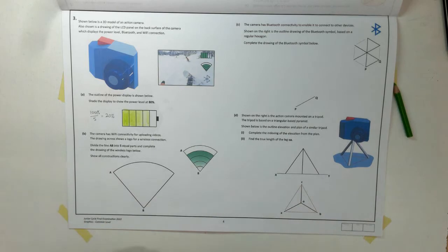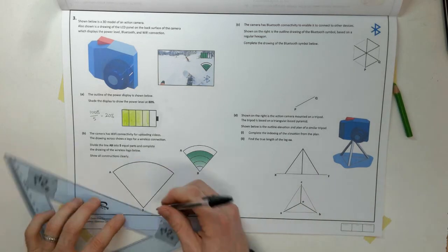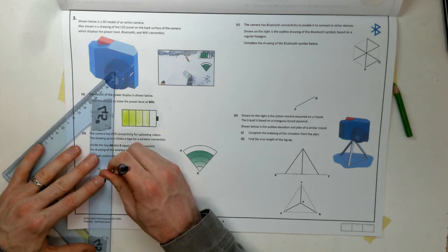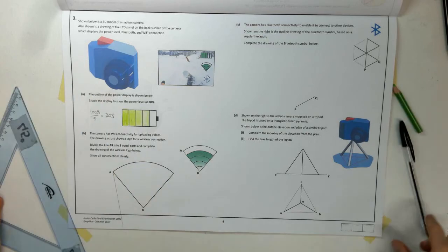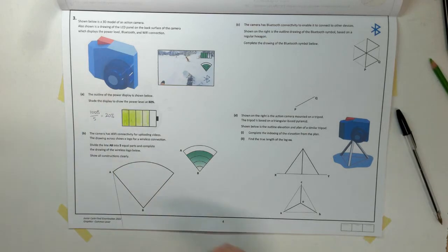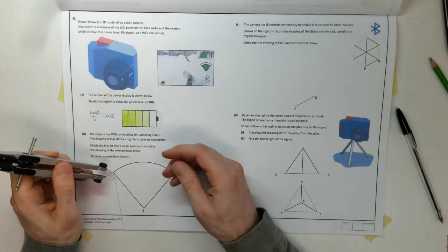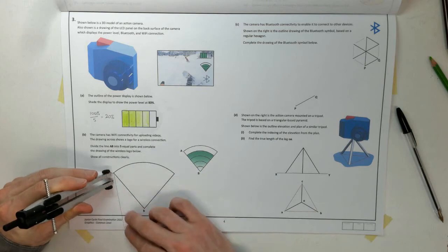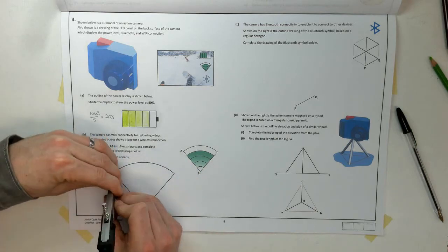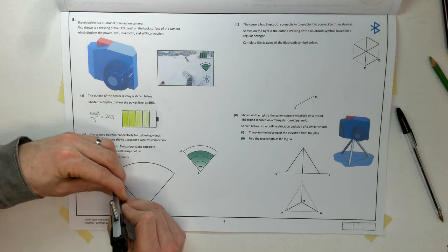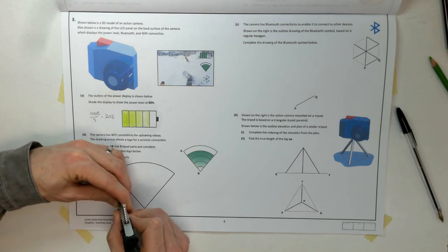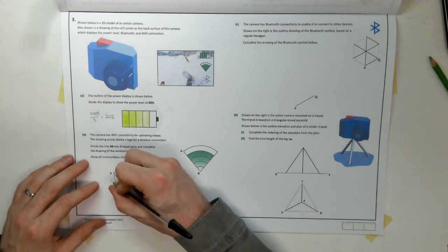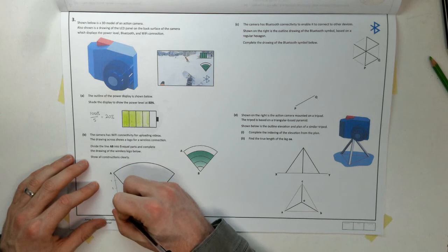So we'll start with dividing into equal parts. We can draw from A or from B, it doesn't matter. I'm going to draw a line at any angle. I'll just draw there, approximately. Any angle you want. I'll get my compass. I'll set it to any distance again, but I want to be conscious that I'm going to step this distance out 5 times, so I want to keep it on the sheet. So 1, 2, 3, 4, and 5. I always number these just to make sure I've got the correct amount.